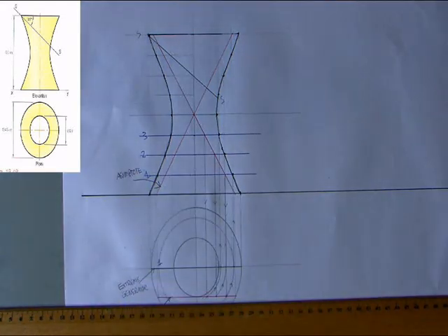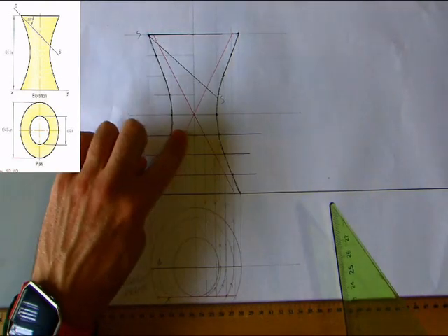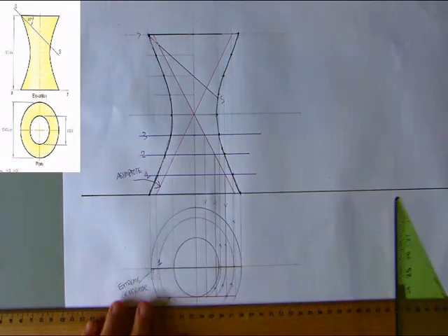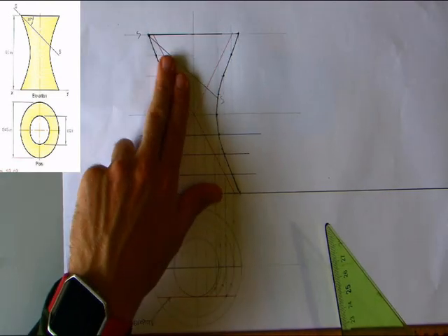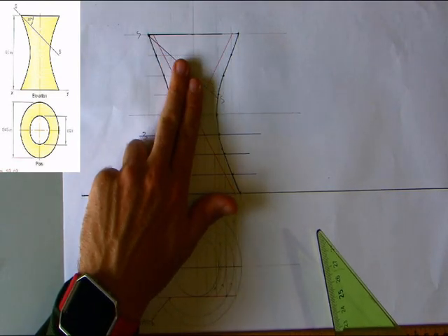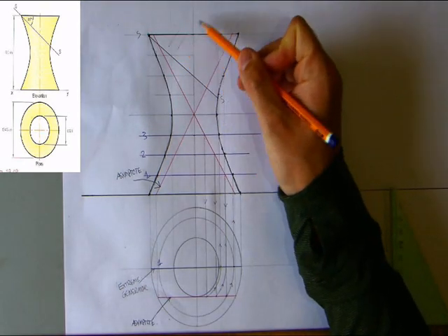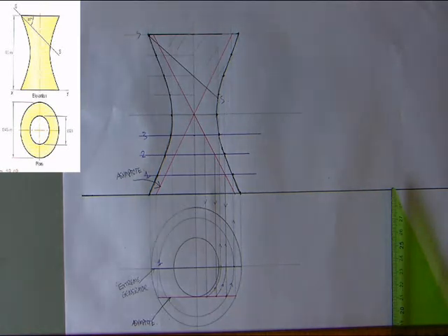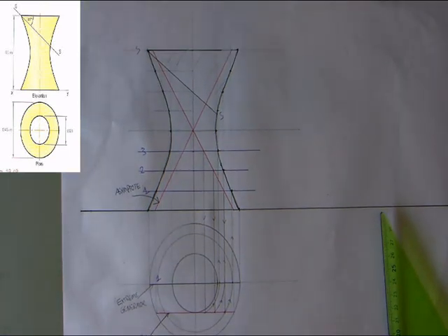And what we're going to do now is use the same idea of the horizontal cuts, and we're going to be creating portions of circles in order to show the shape here. So what's actually happening is this whole part is being removed, and we need to show what's going to end up being an elliptical shape here for the cut.